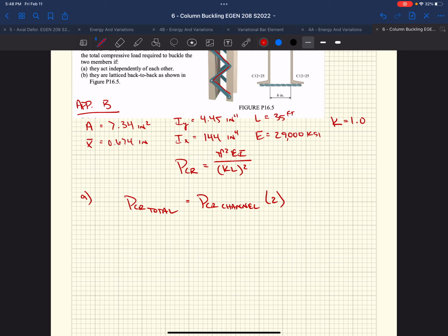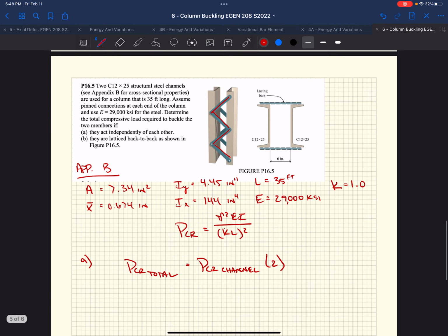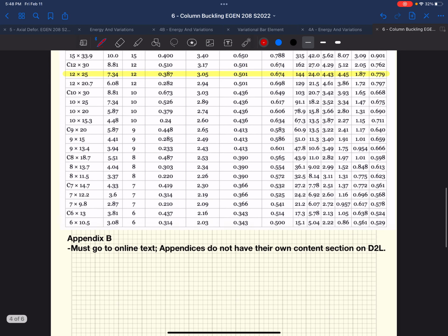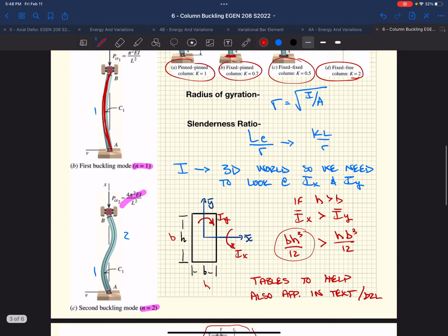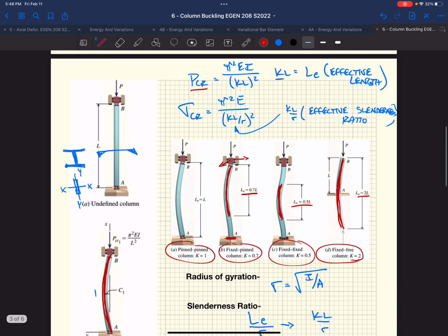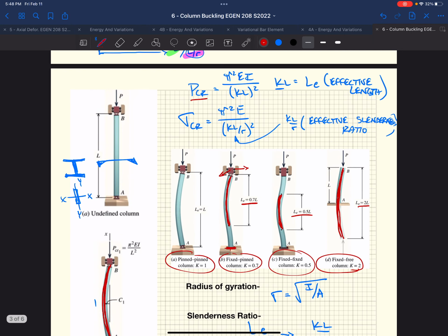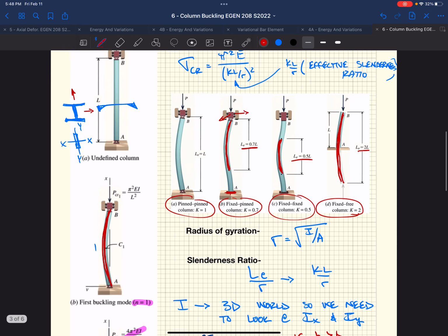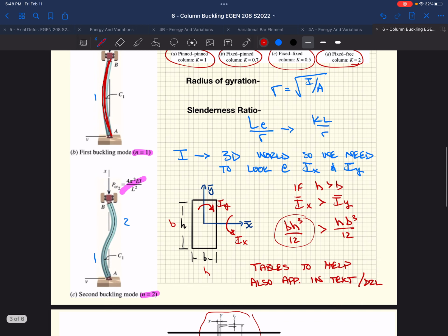Okay. Well, as we know from our previous review, as we started talking about this buckling, this buckling can happen in two directions, right? We could buckle, say in this cross section, one way, or we could buckle it another way. If we were looking at this square cross section, it might buckle to the right, or it might buckle upward on the page, right?